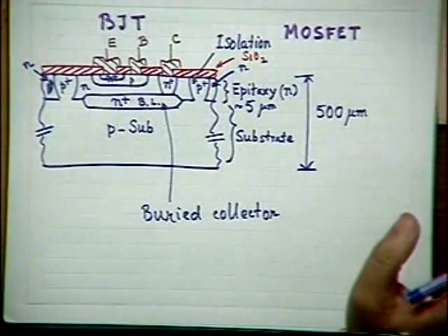As you know, when the transistor handles a lot of current, if the series resistance of the collector is large, then there are two problems. The one is as a power transistor or the driver transistor, there will be dissipation in the transistor, which is not good. And secondly, as a switch, there will be appreciable voltage across the transistor when the transistor is on or in saturation, which we don't need.